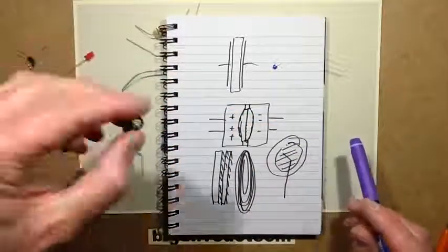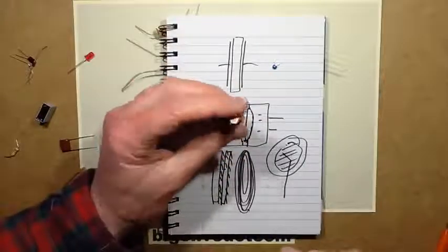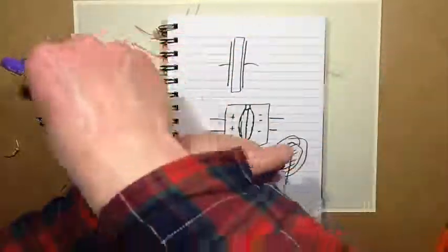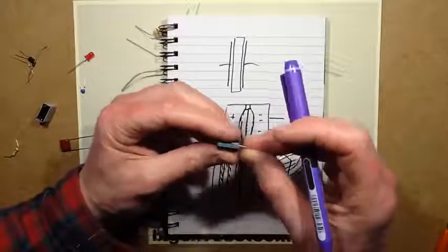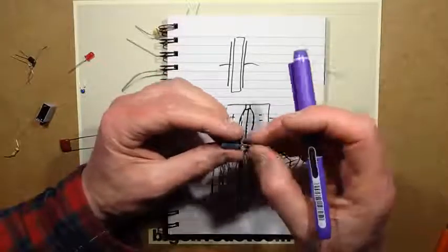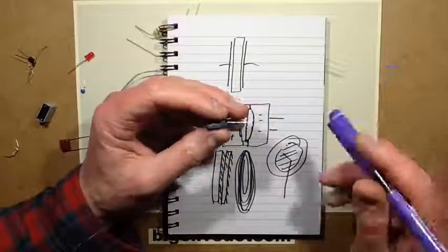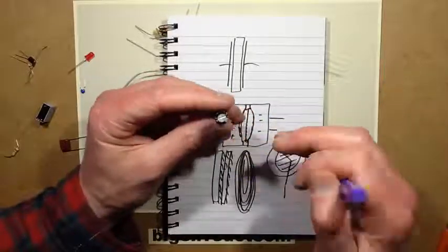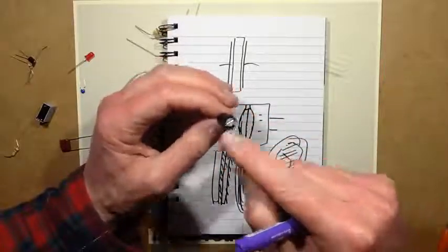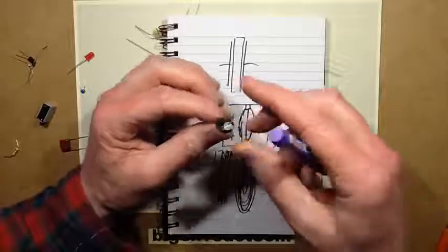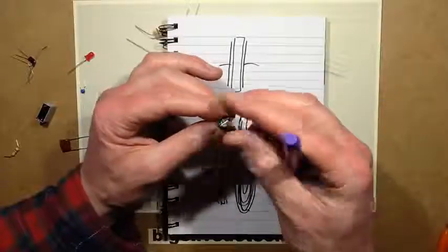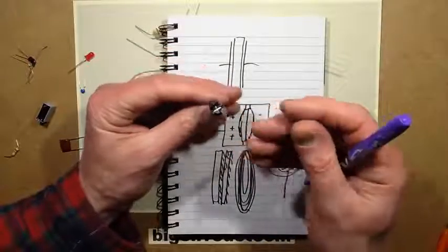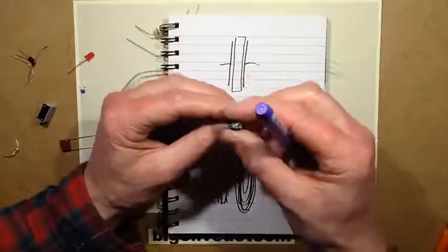So, electrolytic capacitors are one of the more exciting capacitors, and I don't mean that in a good way. The electrolytic capacitors, to achieve such a high capacitance, they contain a liquid electrolyte. And they have a very thin foil inside. And the foil, to create an extremely thin insulator, they form an oxide layer on the aluminium foil in there.